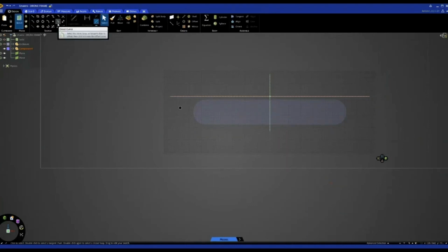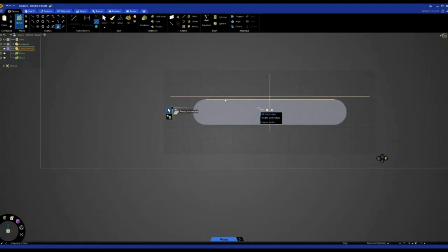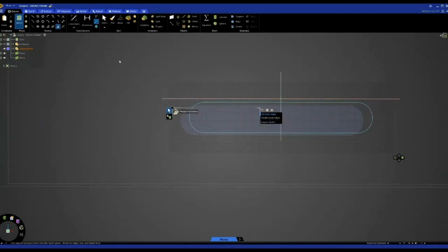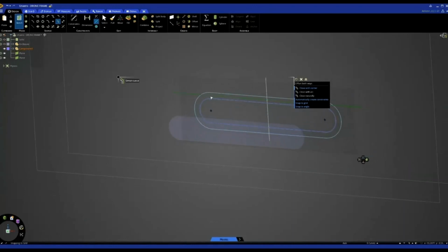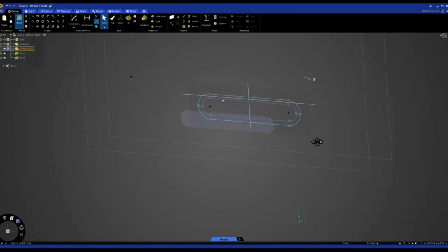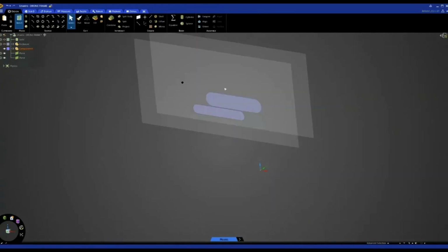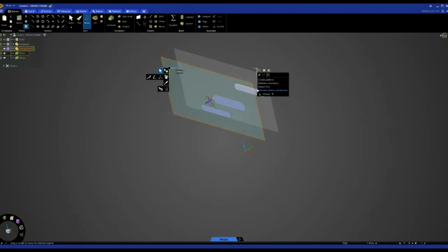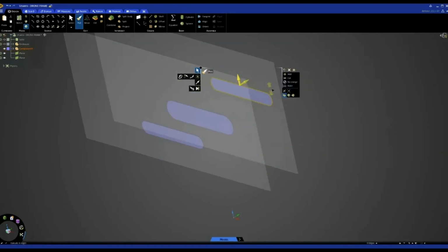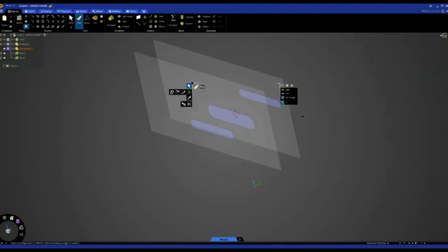And to do that, I'll just project this onto my sketch grid, and I'll use my offset curve tool just to offset these by, I don't know, 10 mil, let's say. So that's my neck shape. Delete these two here. And then I'm going to use my move tool just to move this one maybe to the back. And using my pull tool, I'll make this just ever so slightly smaller. So I'm just doing some basic modeling here. So that might be the profile of my new drone.